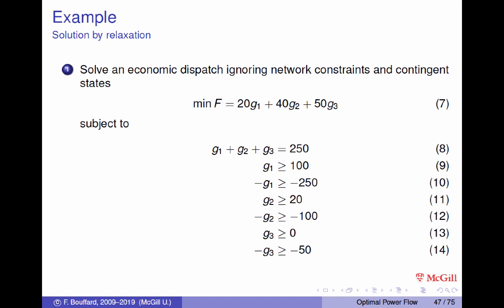So what we're going to do in the next few slides, we're going to actually try to solve this problem graphically. And again, knowing this is a linear program, we know its solution will have to be at a corner of the feasible space described over here. And the other thing that I really want to draw your attention to, if you are trying to minimize cost, when you look at this, you're going to try to maximize the use of generator G1 because it is the cheapest.